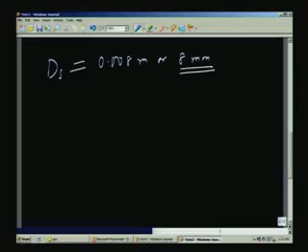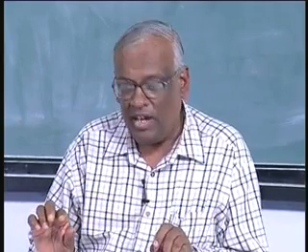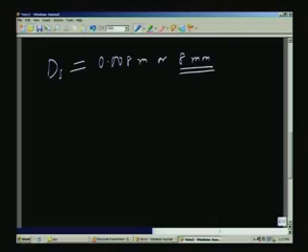So, the diameter of the tube must be at least 8 millimeters or even more, because at 2 meter per second, that velocity is constant. Therefore, 100 milliliter per second will flow through that, but there is a lower limit, so it could be more. That means I have to choose a diameter of 8 millimeters or more. If you want to work at the limit, we can just take a value of 8 millimeters.